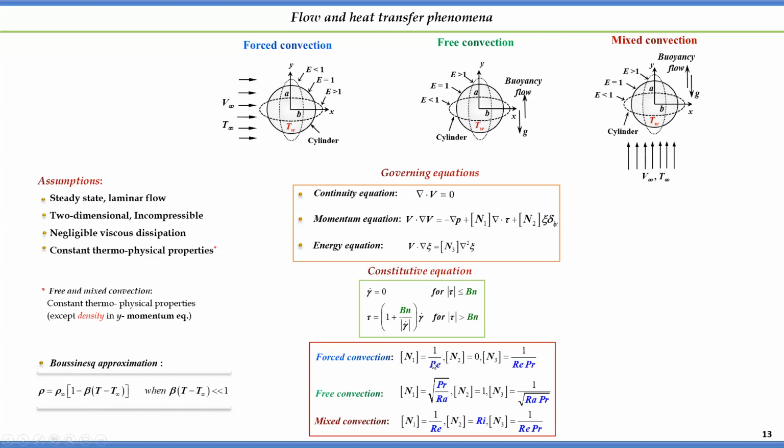That means if you consider a very large range of Reynolds number, which is nothing but rho u d upon mu, you are able to cover the dimensions, that is the diameter of the pipe, velocity, viscosity. You are able to vary all these parameters, get the Reynolds number range, and apply these results over the range of that parameter.